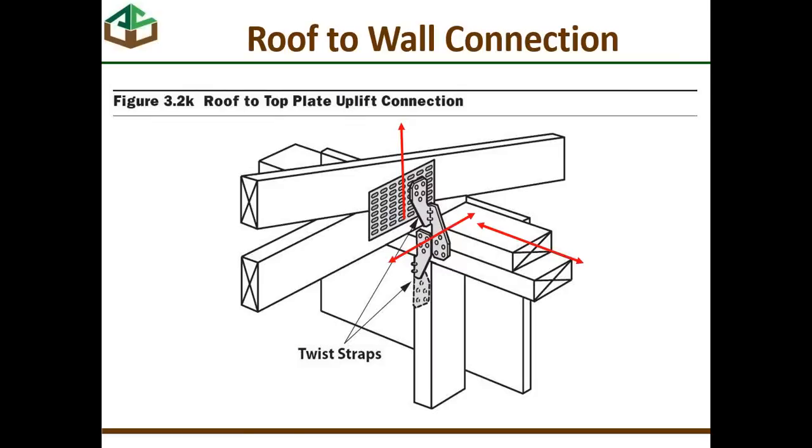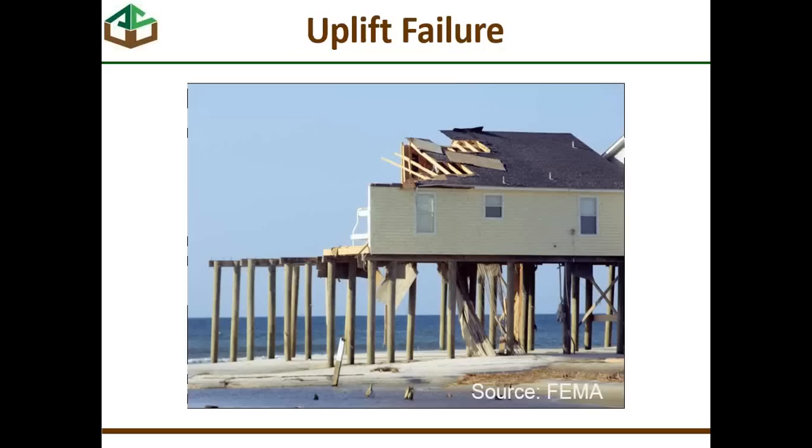And we looked at connections last week. We looked at loads last week that had, in fact, three elements to them. All three of these loads were shown in a table from the Wood Frame Construction Manual: uplift, lateral load, and shear. And those loads are what we would take to a connector table when we're getting ready to find a connection method.